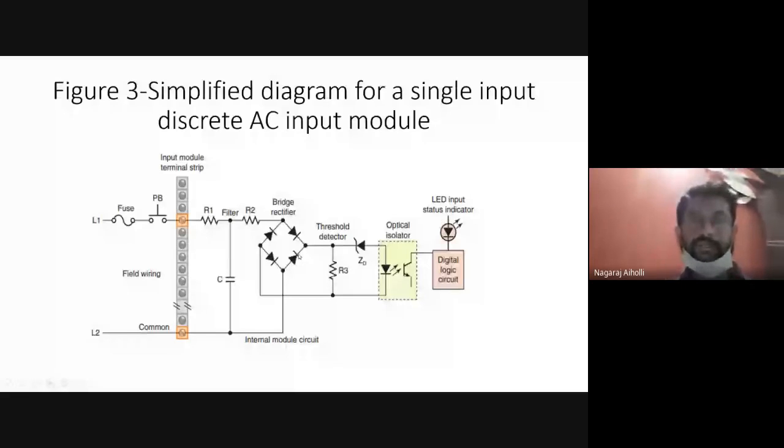Because of this, students, for the positive portion, when the two diodes turn on, the current flows through this resistor. When the other two diodes are on, the current flows in the same direction through the same resistor R3. Because of this, the output that we are getting is only in the positive portion.